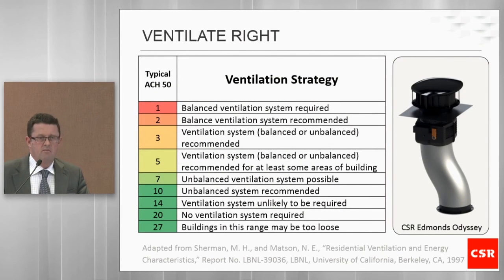It's really important that when we look at making the building airtight, that we also look at the ventilation as well. And the University of California in Berkeley did some studies on this. This is because, quite obviously, if we make the building completely airtight, so if we went to the standard of a passive house of 0.6, we're replacing the air in that building every 20 odd hours. It's obviously going to get potentially stuffy in there. You're going to need to control the air inside that building, because if 50 of us entered into the house today, we're all breathing away, we'd be consuming the oxygen in that building very quickly, pumping out carbon dioxide, and it probably wouldn't be a great party.